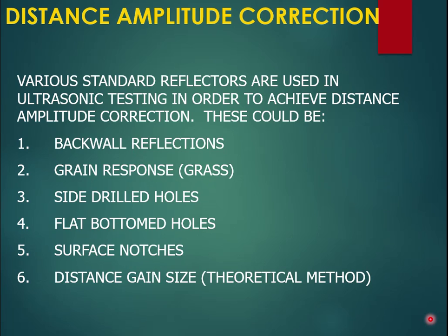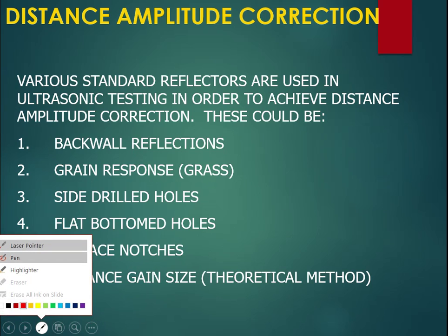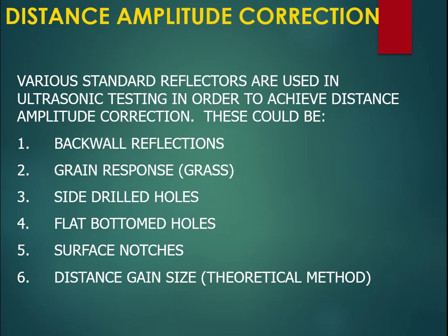We not only consider the amplitude to judge the discontinuity size, we have to consider distance also. Let me explain. For example, I have taken a material which has same size discontinuities but at different distances, and I pass the sound from the initial point, 0 to 100 mm.